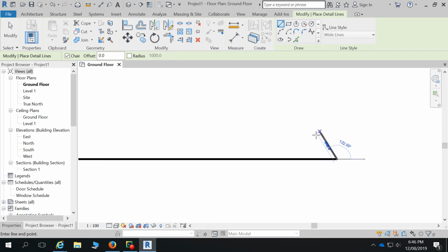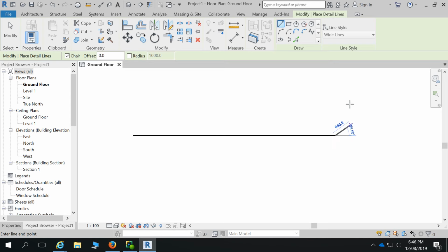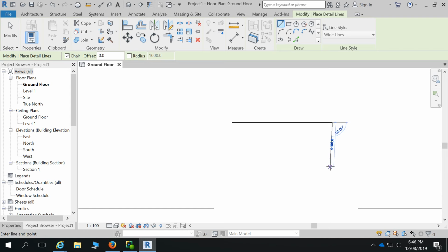What we're drawing matters. So we get some little prompts with Revit is what I'm trying to explain. Depending on where we want to draw, if we want to draw something straight down, we can see that it is 90 degrees. If I hold my cursor there long enough, it's telling me it's coming down vertically on the screen. So straight away I know, okay, that's what I wanted. If it said 91 degrees, I'd think, oh, I'm off axis. I don't want it to be off that 90 degrees.